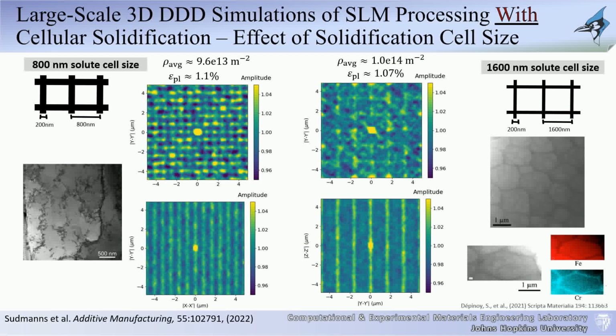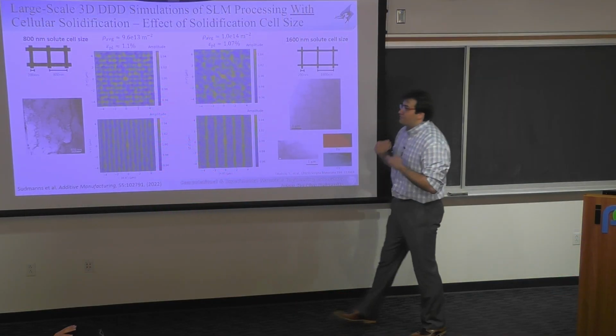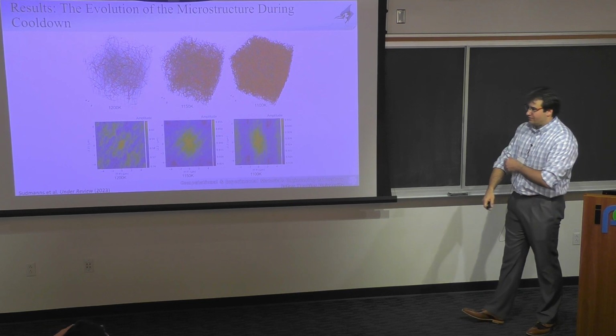For the lower energy, larger cells, you still see those same alignments. But internally, you start seeing patterns forming along 45 degrees, which is the argument that these dislocations are forming not due to solid solution, not due to the solute dislocation interactions, but due to the dislocation interactions themselves. So it gives us a better physical understanding of the origin of this.